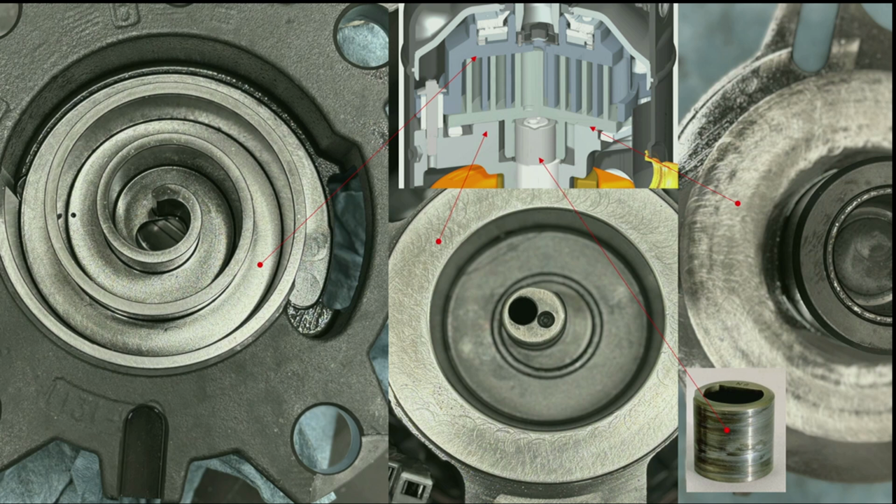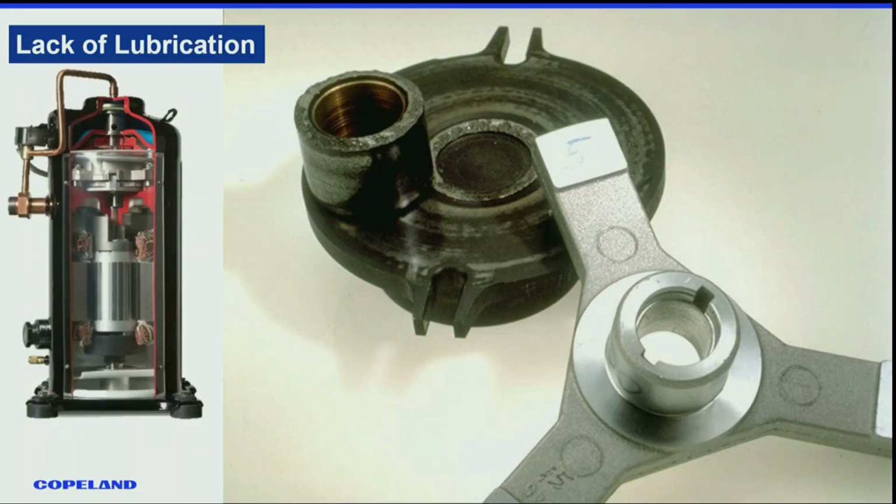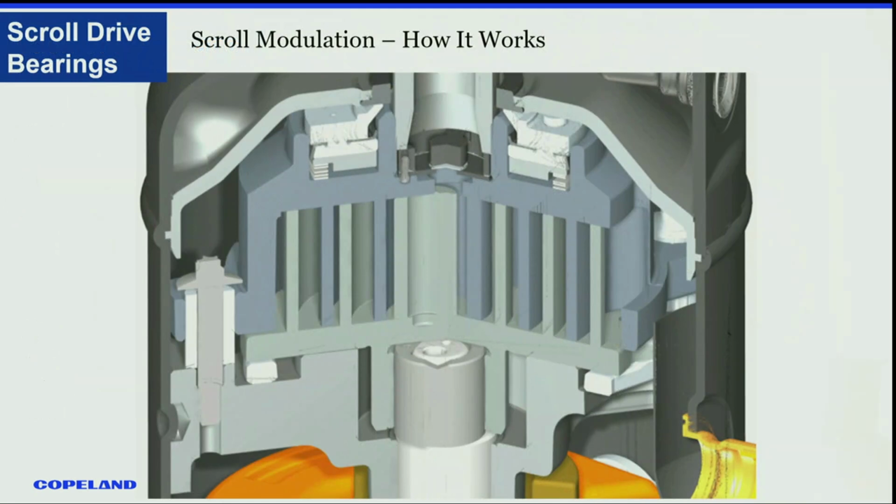And this other surface, you can see they're all scratched up, and they should not look like that when you look inside a compressor. There's been lack of lubrication there. And in extreme cases, that bearing could get sheared right off in the 3-phase compressor when it loses complete lubrication. So while that's the top bearing, this one didn't look so bad. So it had oil and CO2. That one got nothing because the CO2 boiled off by the time it got up to the top. That's really what that's showing.